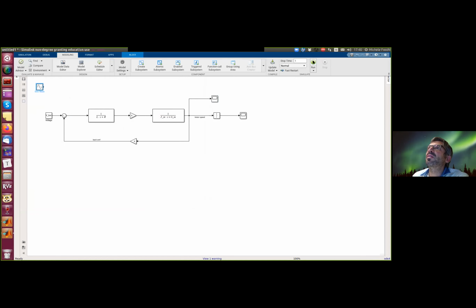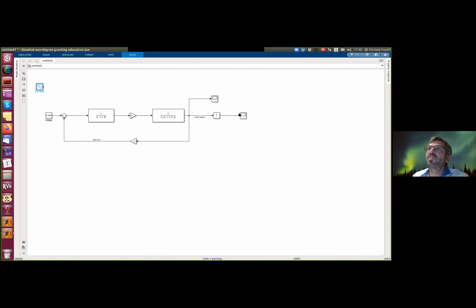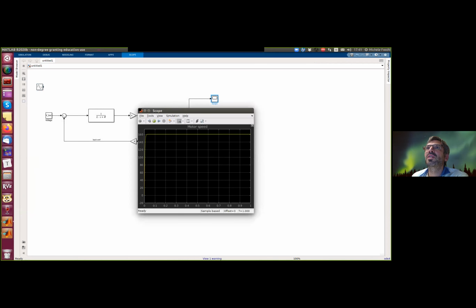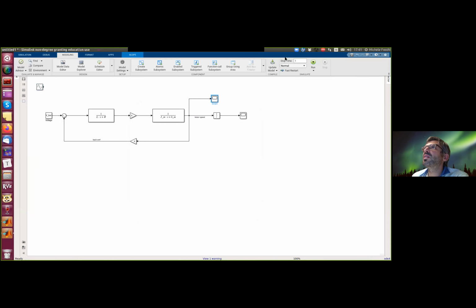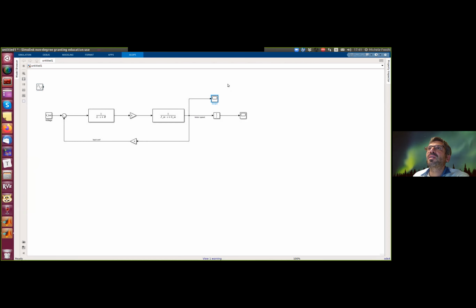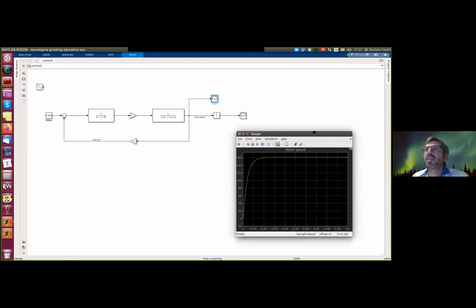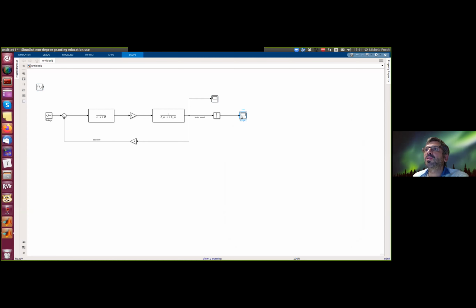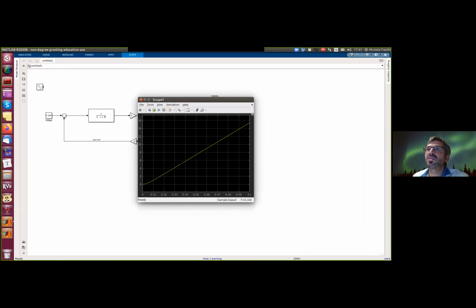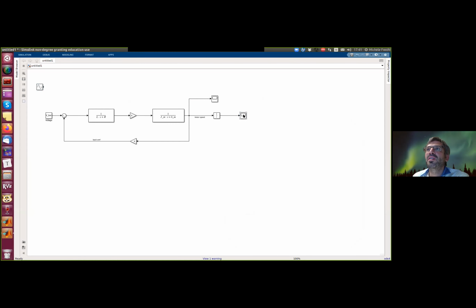Otherwise, Simulink will do it automatically, find the best one with a variable step solver, but this is not good for what we see later, that is the sensor quantization problem. So now modeling 1 second is still too much, maybe 0.1. And with 0.1, we can see the speed that goes to the steady state value and the motor position that after an initial acceleration goes to constant velocity.